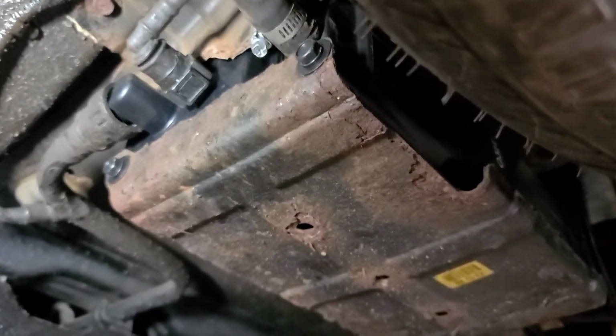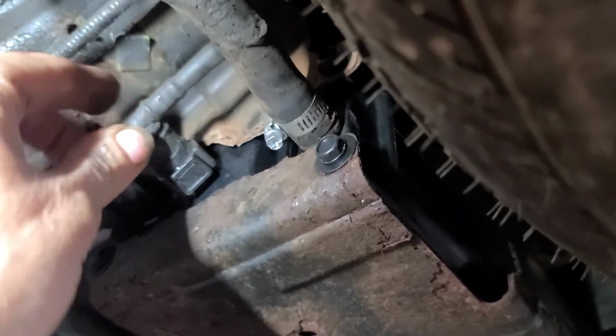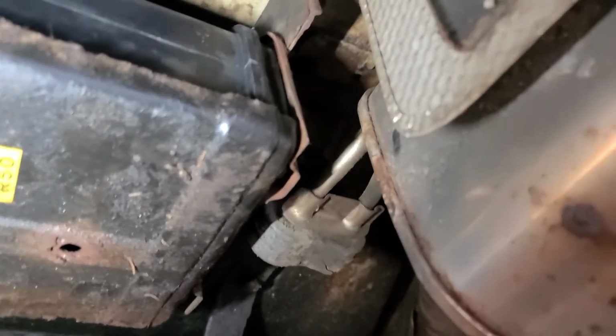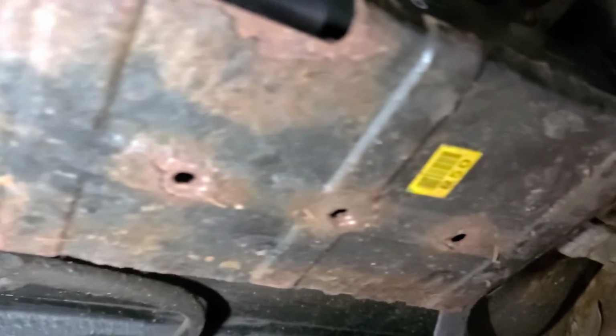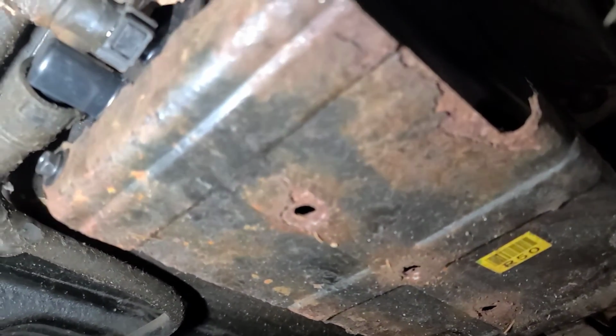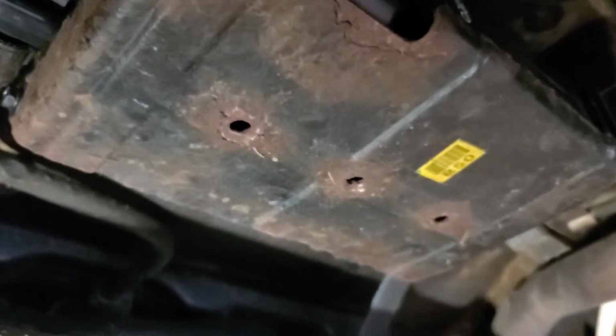So let's get started. So there's the new charcoal canister installed. I changed these hose clamps here because they were rusty. Dielectric grease on the fittings and connect them back in. So as I said, you had to reuse this shield and mounting straps. You just got the canister with the part. So we're going to smoke test it.